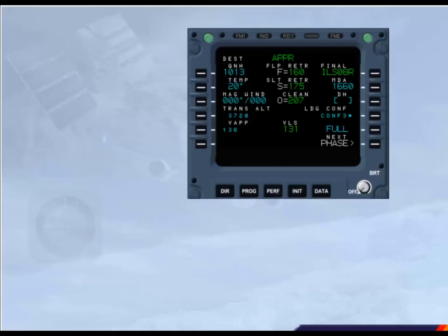Flap 3 is a recognized landing configuration. If the option is used or if required by an ECAM procedure, the crew should select Landing Configuration 3 on the MCDU to ensure that the GPWS does not generate warnings when it detects that the aircraft is not in the full flap configuration.